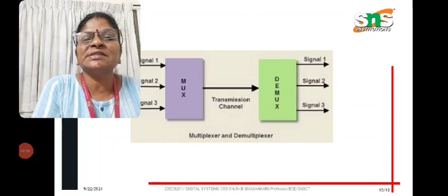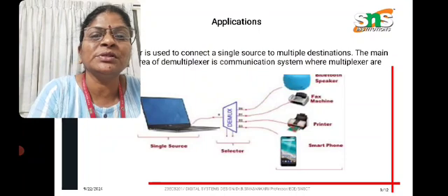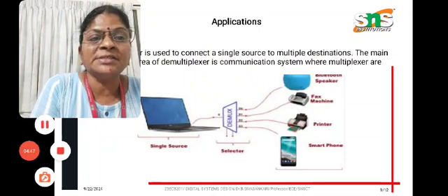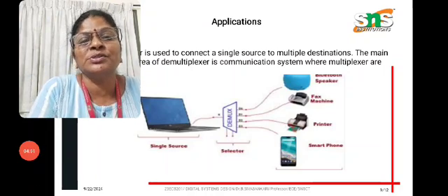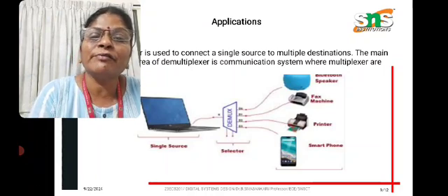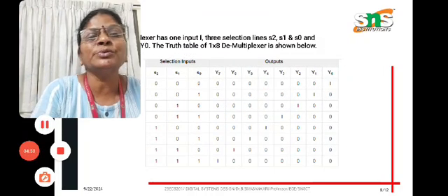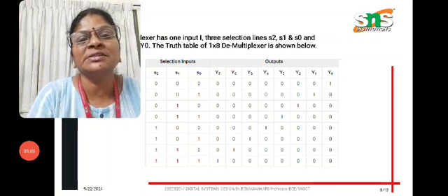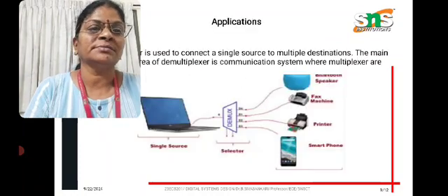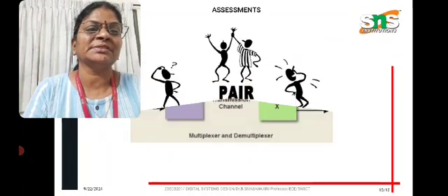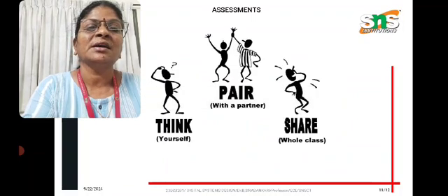These are a few applications of the demultiplexer. So 1 cross 16 is nothing but a single 1 cross 2 with dual 1 cross 8 demultiplexers, so that we can get 16 outputs from one single input with 4 selection lines. The outputs are received in the same diagonal aspect. So these are all about the demultiplexer, as well as what we discussed about the multiplexer in the previous session. Thank you all.